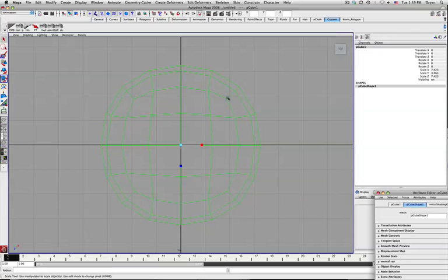And we're going to use some joints, just as things that we can grab and move around easily, because when you have a joint in a piece of geometry, if you marquee select over them, the joint will always be selected preferentially. You can see that up here in the status bar. This shows all the things, my selection masks, so they're all clicked on, so it means I can select any type of object in the scene.